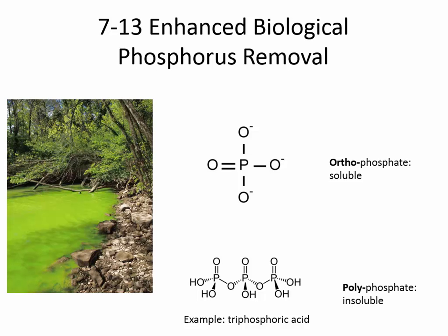And you don't want to have rusting of the pipe, and so having the water precipitate a very thin layer of calcium phosphate onto the pipe. Over the long term, over 30, 40 years, the pipe will get covered with scale, but that's better than having the pipe corrode and rust through.